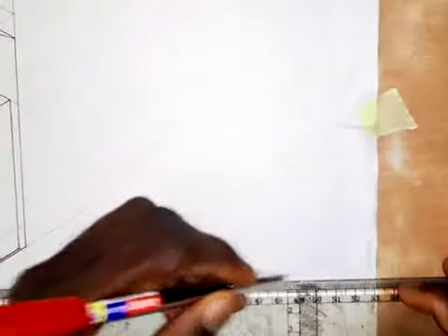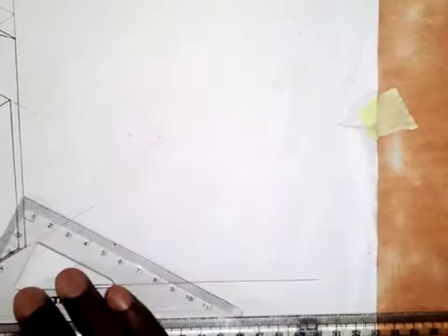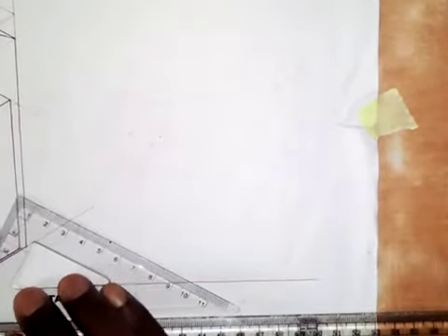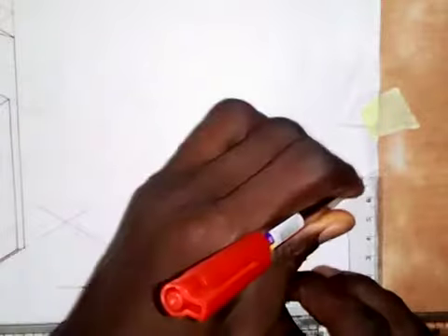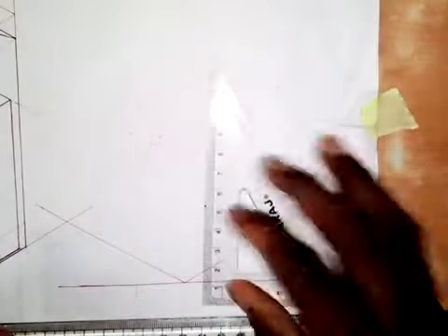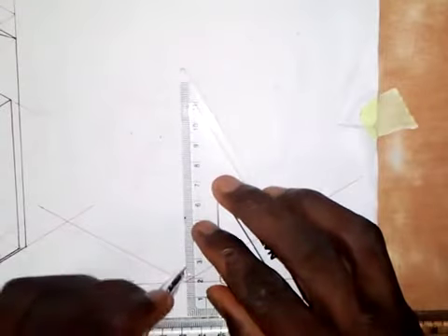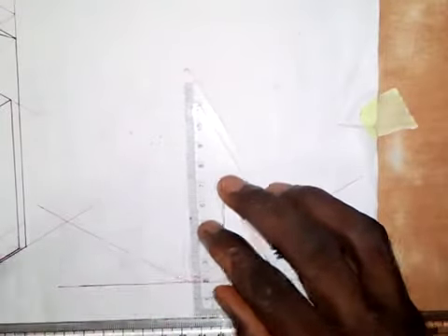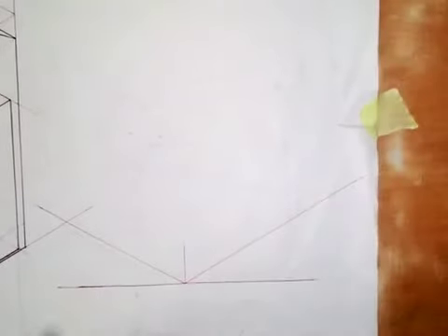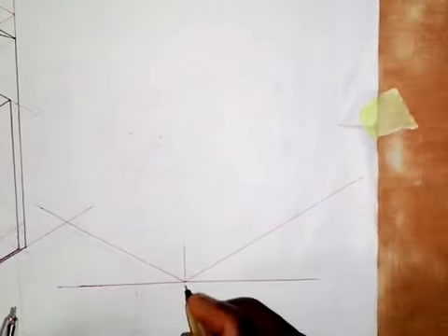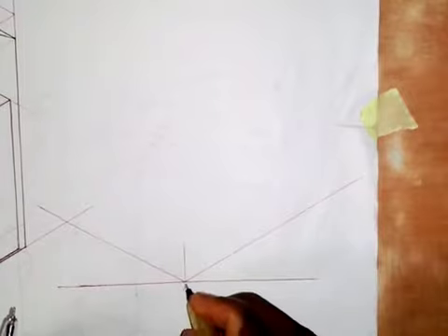The first thing that we need to do here, as you can see, is to draw a horizontal line in this direction. Draw a horizontal line, and then with your 30-degree set square, I'm going to draw a line in this direction. Then I will also draw a line in this direction. Don't forget that I said that we are drawing half size of the given dimensions. So I will take a vertical line up here a little bit like this. And this is point A now. In my own drawing, this is point A as we are given there. So this is point A here.